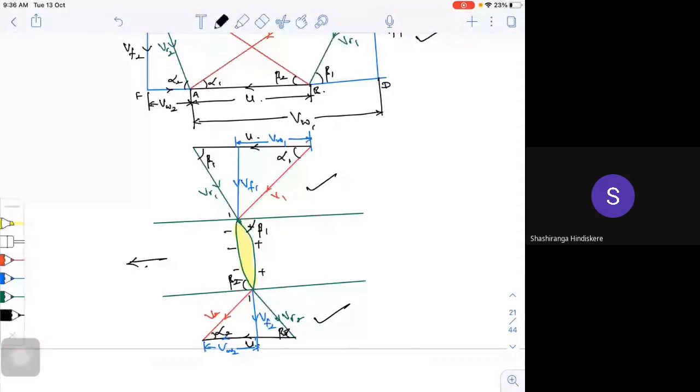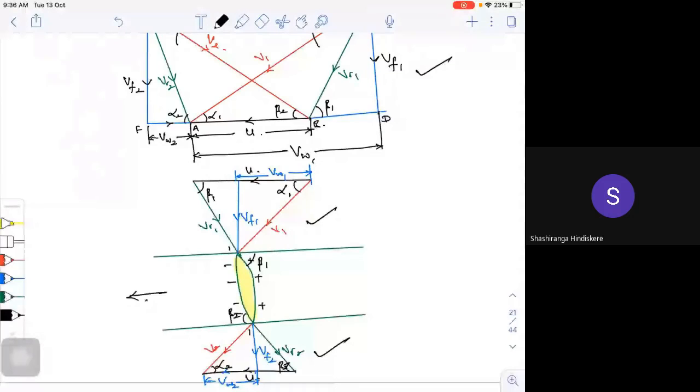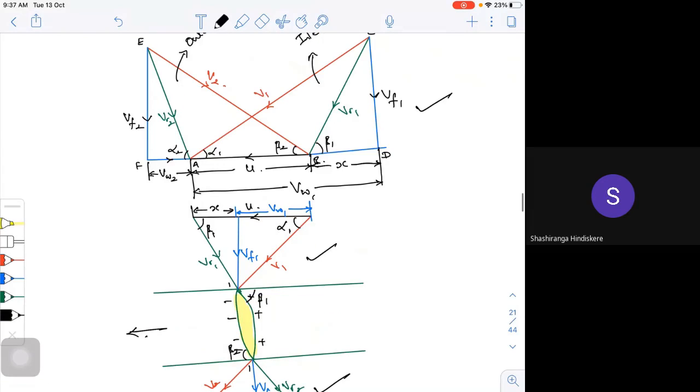So what is my sine alpha 1? It's once again Vf1 divided by V1. And what is my cos alpha 1? It is Vw1 divided by V1. So I can find my flow velocity and whirl velocities at inlet, similar to what we found in the previous problem. If I call this x, this is x here, and this is x here. After I solve the problem, you can cross check using both, because I'm using trigonometric principles and nothing else, we'll end up with the same solutions.